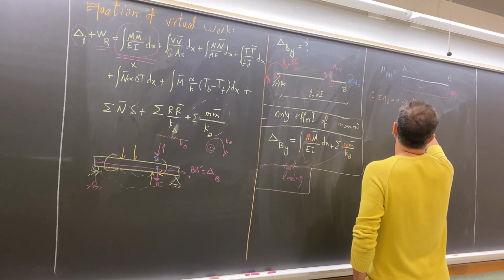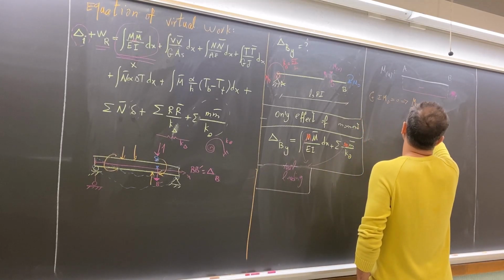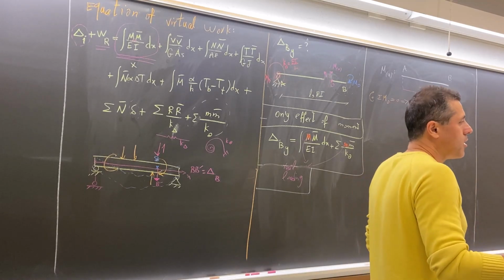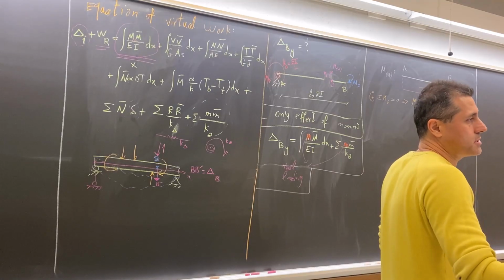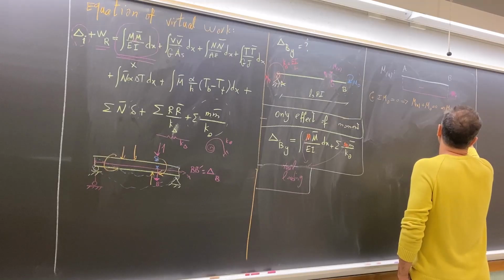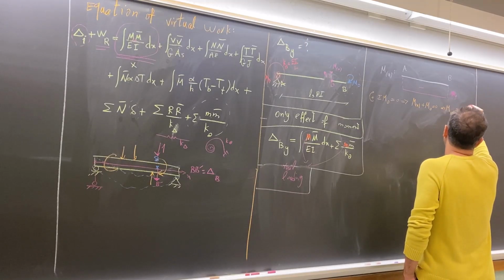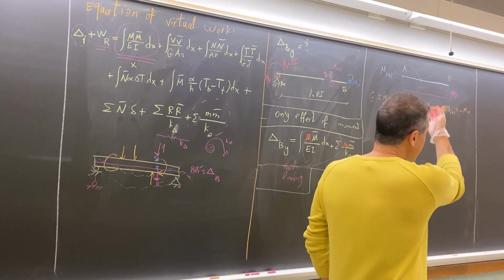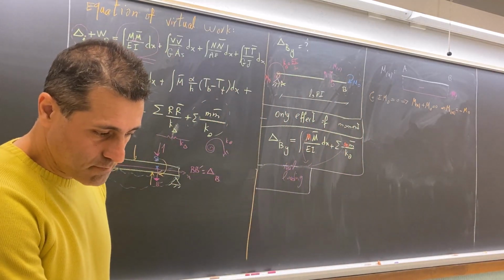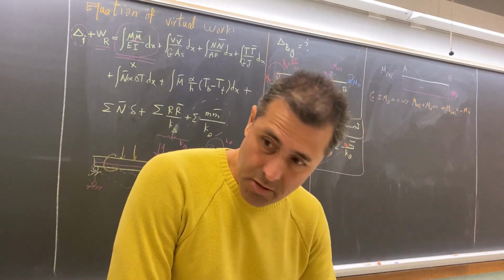Then Mx plus M0 is 0. M0 is a parameter, for example, 10 Newton meter. It's a moment. So from here, the equation for Mx is derived: negative M0. And then that one is the drawing. Simple. Any question?